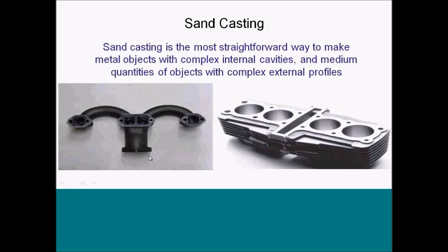So in this kind of circumstance, cast iron is a very good option for these types of parts, and we can make them relatively cheaply and in high volume. This is all cast in one piece, and then we perform some machining operations to flatten some of these surfaces so that they can bolt up and seal nicely against the head of the car and also against the exhaust manifold.